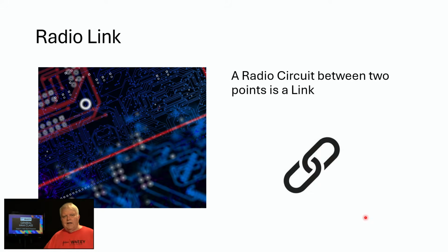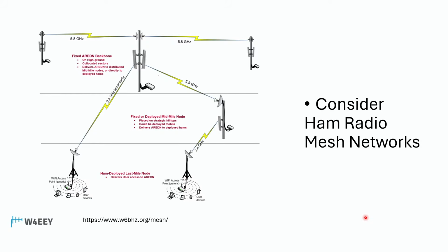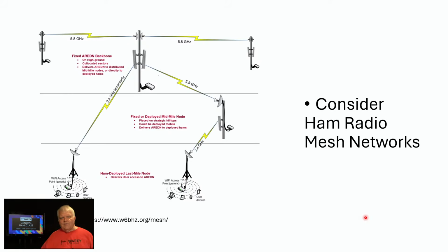And in amateur radio, one of the shared bands that we have shared with Wi-Fi, 2.4 gigahertz, or the 13 centimeter band, amateur radio operators are putting up what we call mesh networks, or an independent linking of modified routers using amateur radio call signs and amateur radio software. And so ham radio mesh networks are point to point. So we need to actually start thinking like telecommunications companies when we're putting these things together.